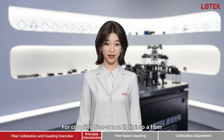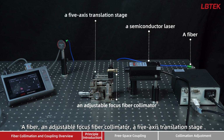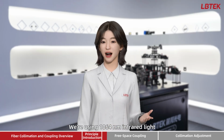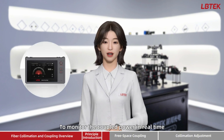For coupling free space light into a fiber, you'll need a semiconductor laser, a fiber, an adjustable focus fiber collimator, a 5-axis translation stage, a fiber holder, and a near-infrared detection card. We're using 1060 nanometers infrared light. Besides, you'll also need a power meter to monitor the coupled power in real time.